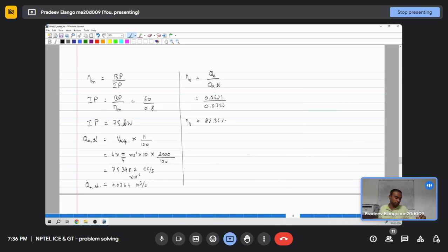So, we have this system here. Generally during compression the pressure inside the cylinder will go high, and during expansion it will keep decreasing from the peak pressure. This can be represented in a PV plot like this, a pressure-volume plot. Starting from BDC, the pressure will be low and the volume of the cylinder will be high.